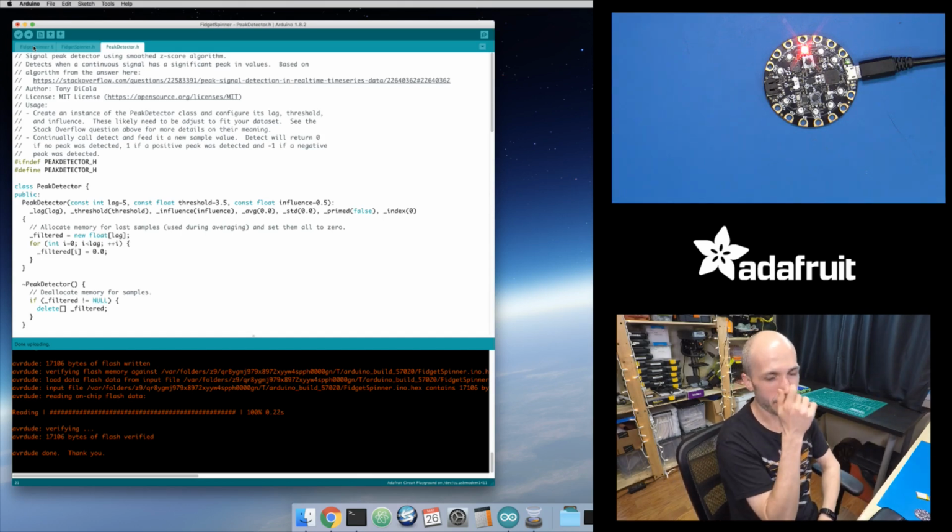So I'm not sure, because the problem with CircuitPython is you're running interpreted code, so you're not going to be able to sample that accelerometer as quickly in Python code. So I might have to play with a few different options to see if I can sample it fast enough, or if I can't, maybe I can just use the tap detection. I won't be able to detect the direction; I'll just know if someone touched or tapped the board.